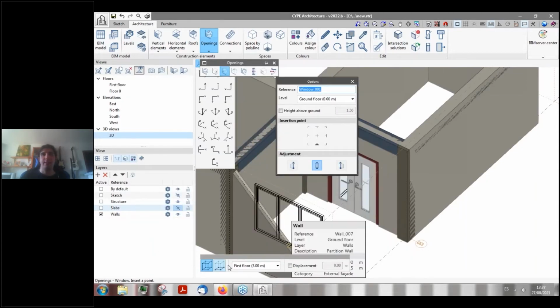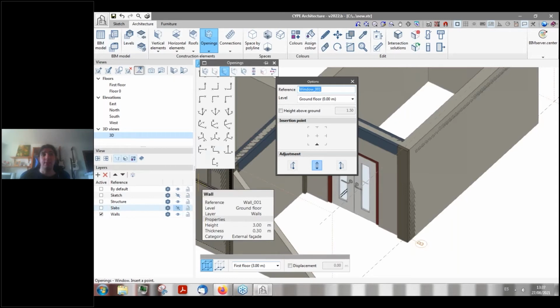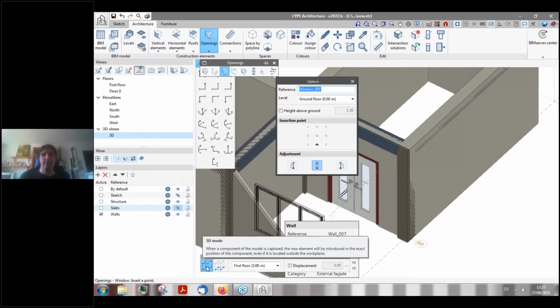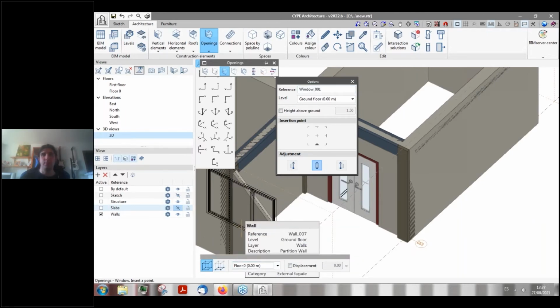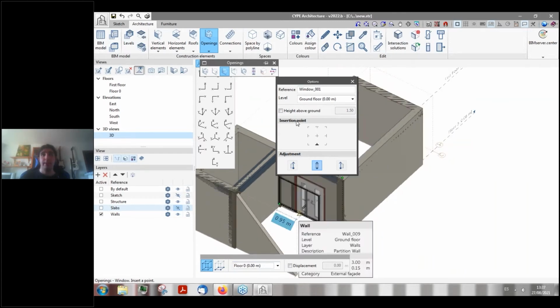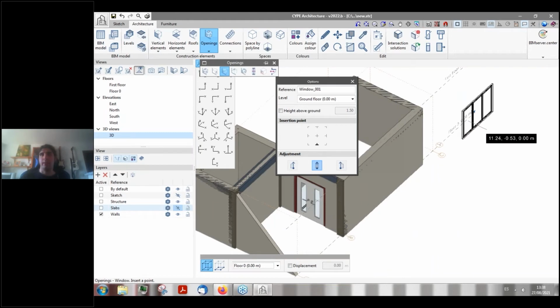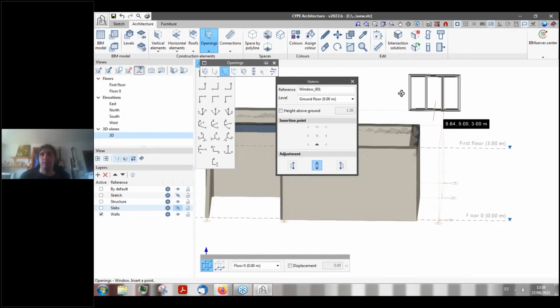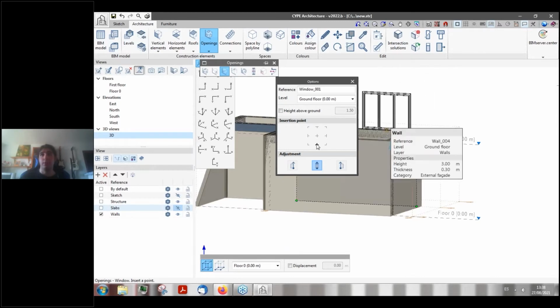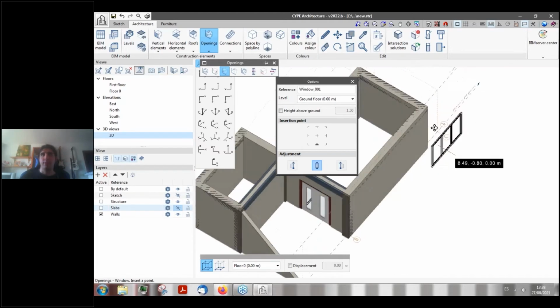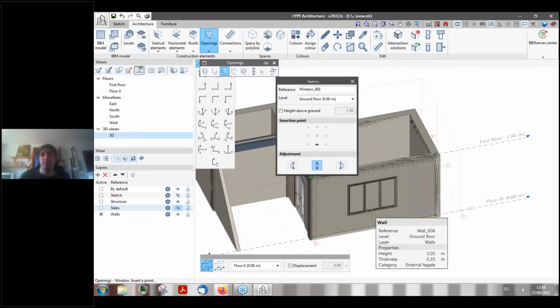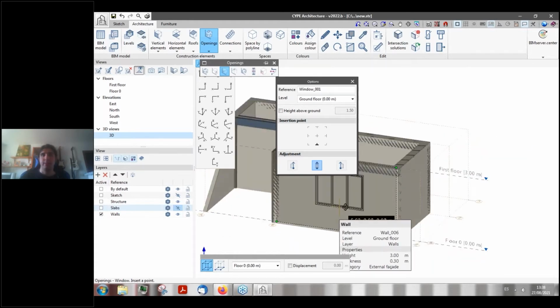As you can see here, I'm working first in a 3D view with 3D mode activated, and I'm going to set it into floor 0 for the BIM model. Now you can see that the insertion point is set by default on the middle lower part. And if I scroll around my model, you will see that the window does indeed snap to my cursor on its lower middle part. So if I were to insert it freely on the 3D space, like so, you would see that I could set whichever height I want.